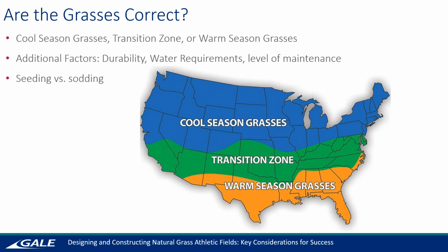So you just got to be mindful what has typically been successful in your area, and use those types of turf grasses, right? Typically in the warm areas, we're talking primarily Bermuda, and in the cold areas, we're leaning more toward Kentucky Blue, and then mixing it with different types of rye.